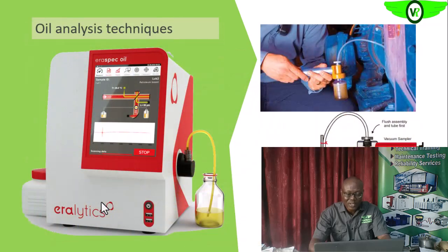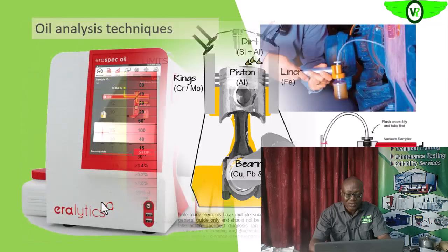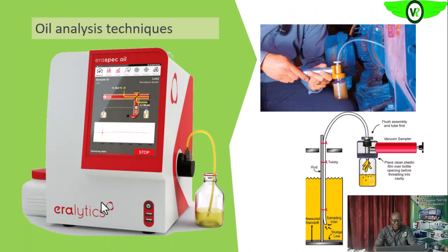So let us look at the major techniques that we go through in carrying out this lube oil analysis. For you to analyze the oil, first you have to take a sample of the oil. Your sampling points need to be fixed. That is, each time you go to take a sample, it must be from the same spot or the same point on the equipment. Are we getting it?